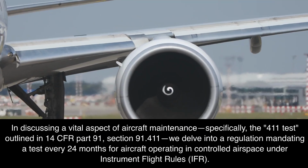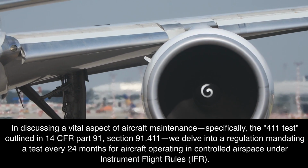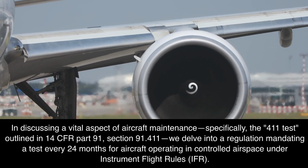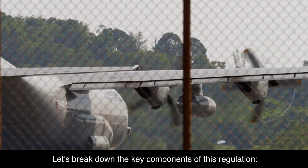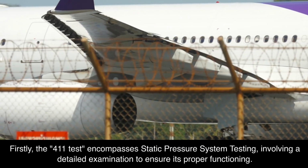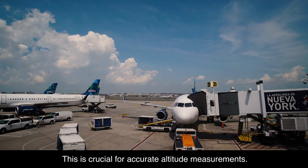In discussing a vital aspect of aircraft maintenance, specifically, the 411 test, outlined in 14 CFR Part 91, Section 91.411, we delve into a regulation mandating a test every 24 months for aircraft operating in controlled airspace under Instrument Flight Rules, IFR. Let's break down the key components of this regulation. Firstly, the 411 test encompasses static pressure system testing, involving a detailed examination to ensure its proper functioning. This is crucial for accurate altitude measurements.